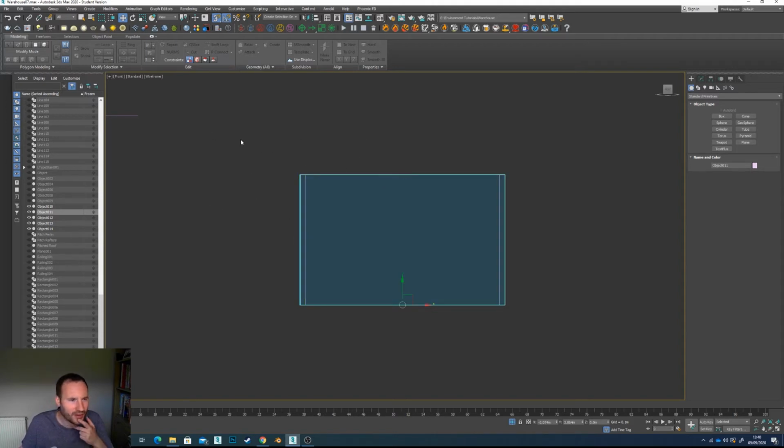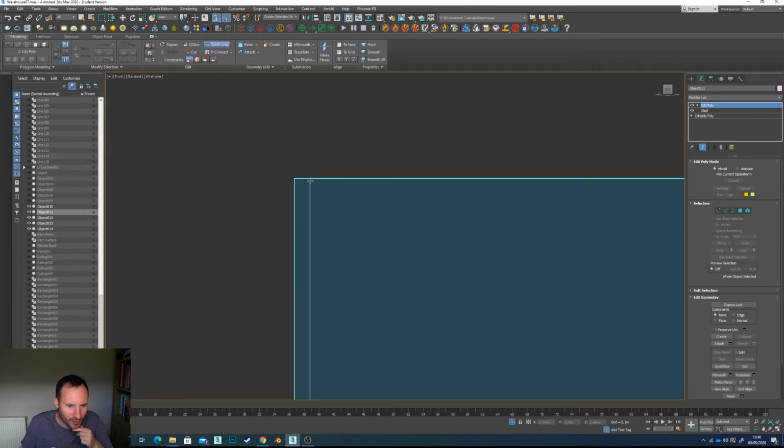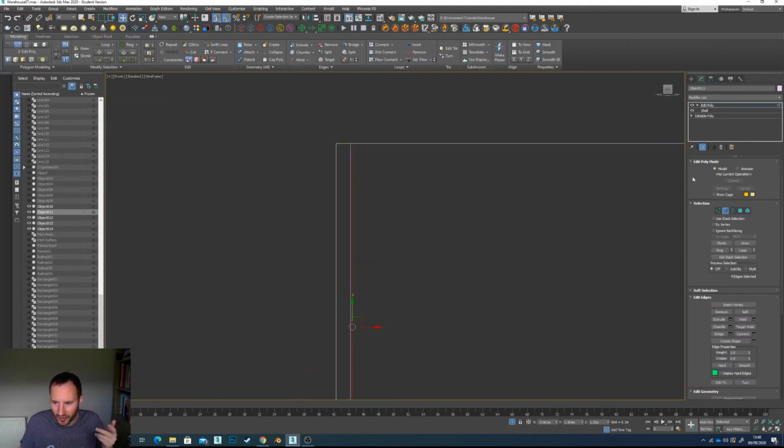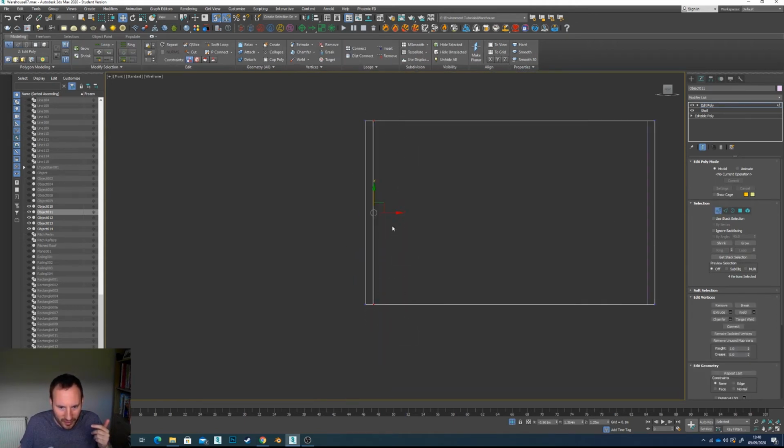What I'll try and do is I'll just go to the edit poly, make sure I've got that selected. You see we've got our modeling tools. Now we might be able to, I'll just pop it in because we know that the Swift loop doesn't snap to things that are further back, but once we've made it, we should be able to pop that in. So let's just see, hopefully it will. Yep, so it's snapped there now.